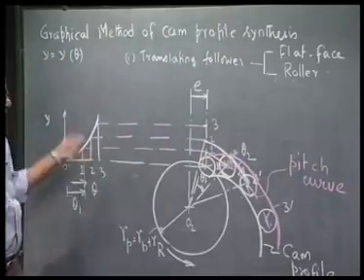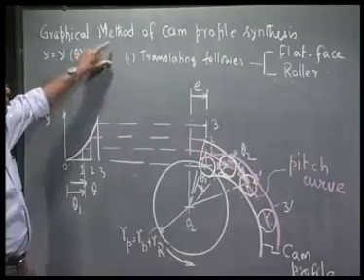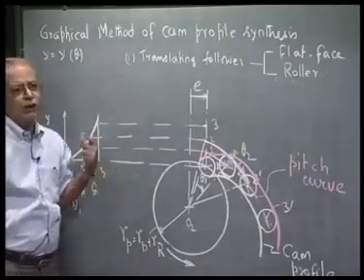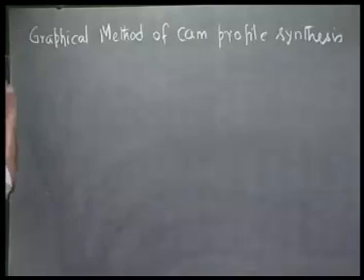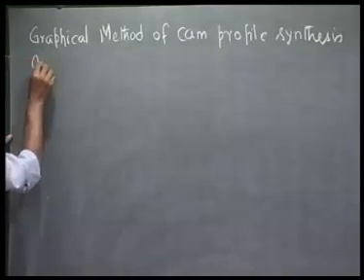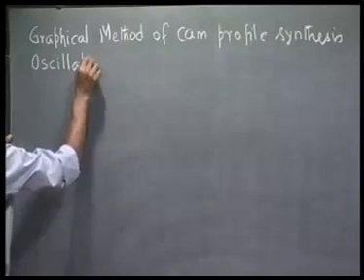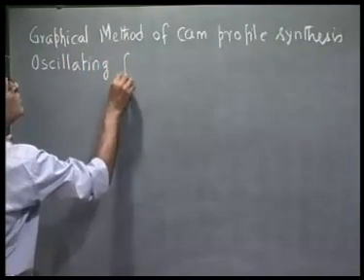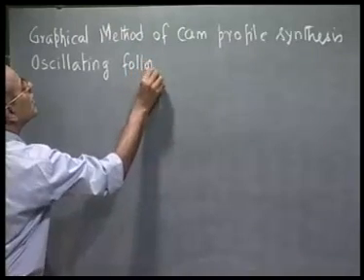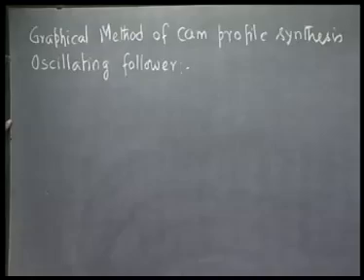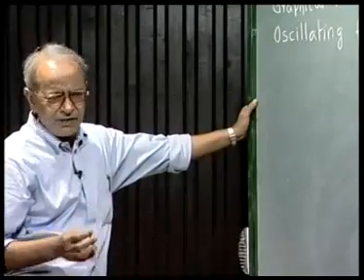Next, we will show how to use the same principle to obtain the cam profile for an oscillating follower, either roller or flat face. Let me now explain the graphical method of cam profile synthesis with reference to an oscillating follower. Here again we shall discuss both roller follower and flat face follower.